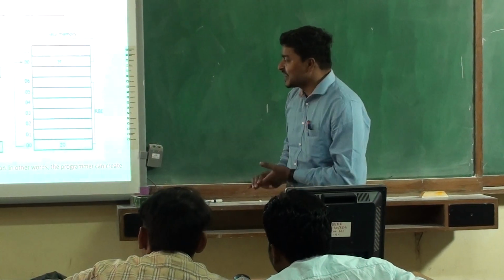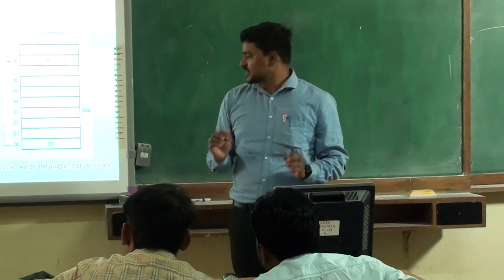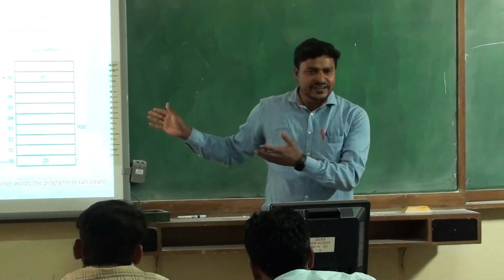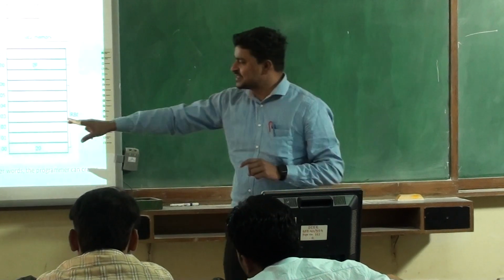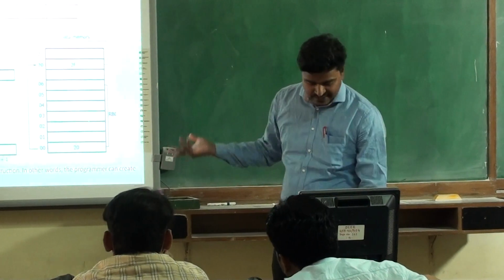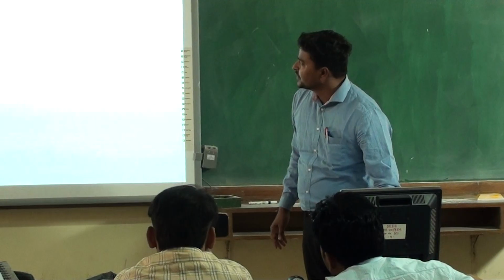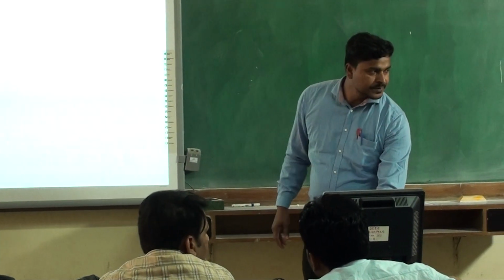Only R0 and R1 are allowed in register indirect addressing mode because this is a pointer kind of thing; we are pointing to some data using the register. So only 2 registers are allowed, and this is the limitation of this particular addressing mode.